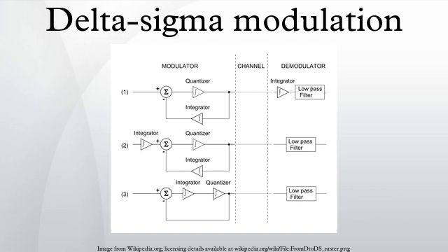The resulting two-level signal is now like the desired signal, but with higher frequency components to change the signal so that it only has two levels. These added frequency components arise from the quantization error of the delta-sigma modulator, but can be filtered away by a simple low-pass filter. The result is a reproduction of the original, desired analog signal from the digital values.